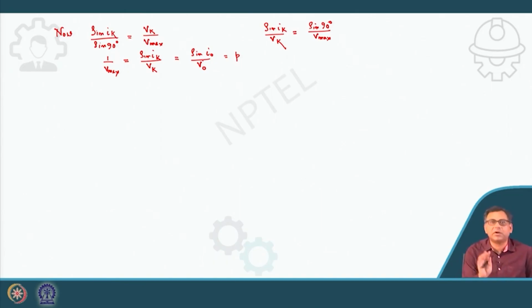Similarly, V_max is also not constant, it varies with the distance of the geophone from the source, because if the distance of the geophone from the source is high, then the ray will reach a higher depth, so the V_max, or velocity, will increase. Similarly i_0 is not constant, it depends on the ray.